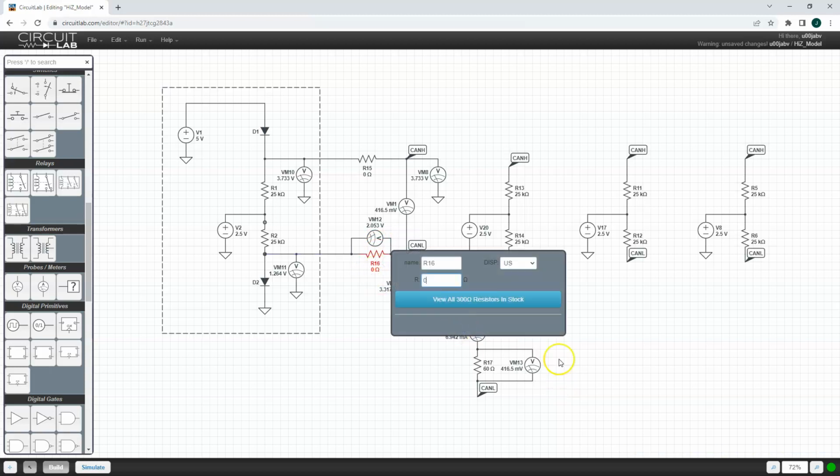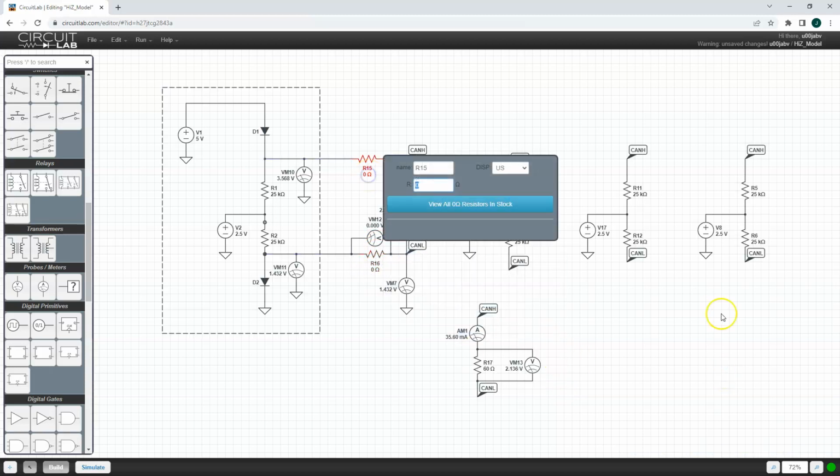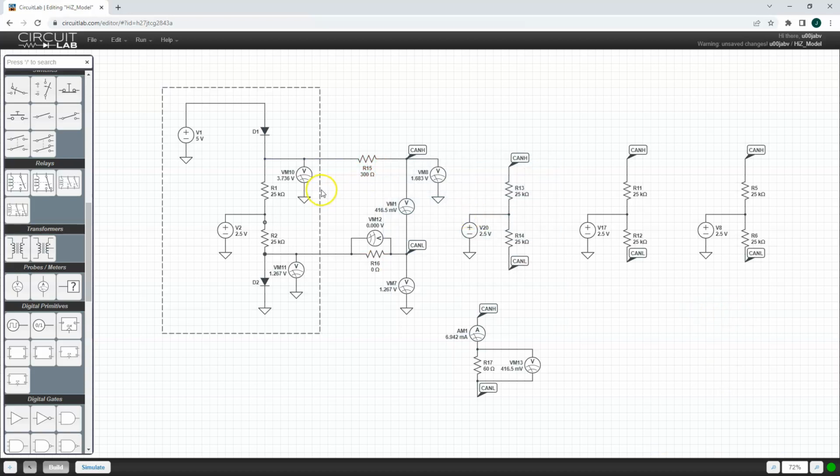If I were instead to do this and go the other way, what I will see is it will do the same thing. I put the 300 ohms up here. If I were to take my meter up here instead and drop it across it and see what it's got, I'm going to do the same kind of thing. This voltage is going to be dropped across this guy, and it's backwards because I stuck the meter in wrong, but there we go. I'm dropping the 2 volts on the high side now.